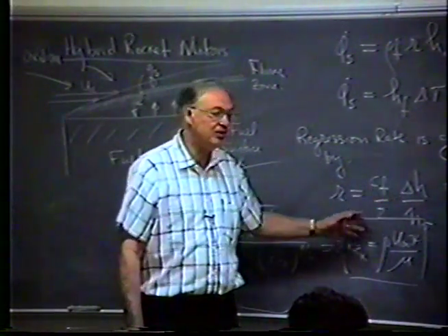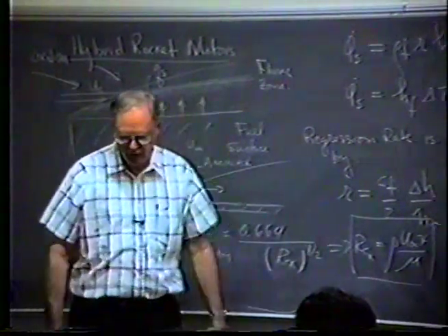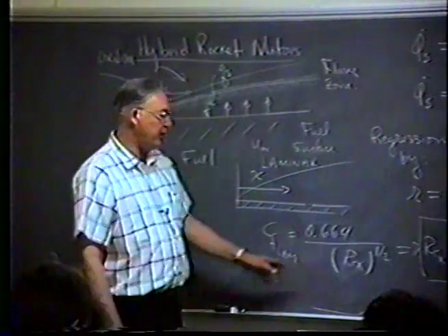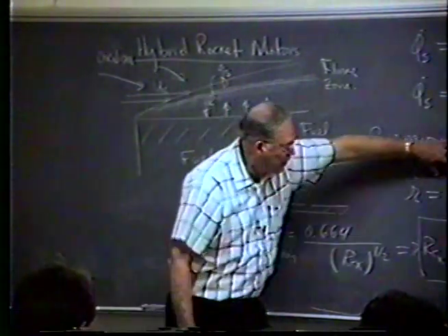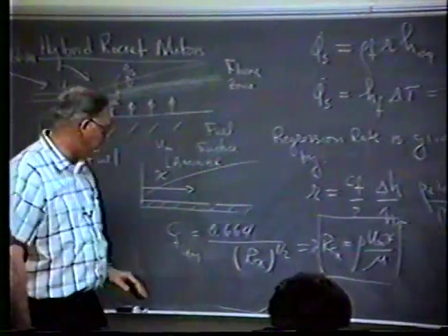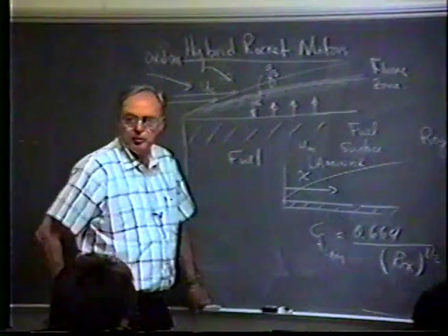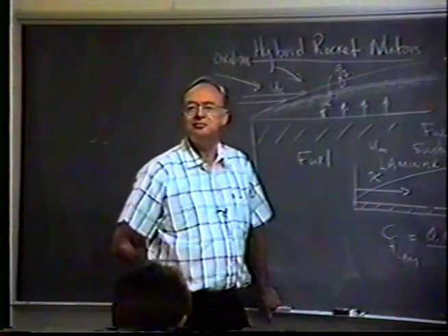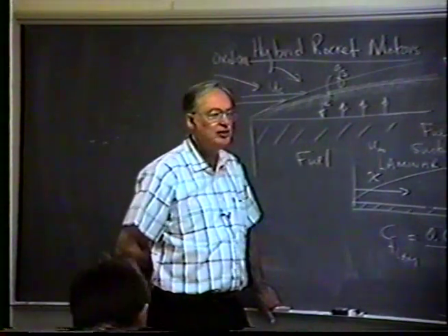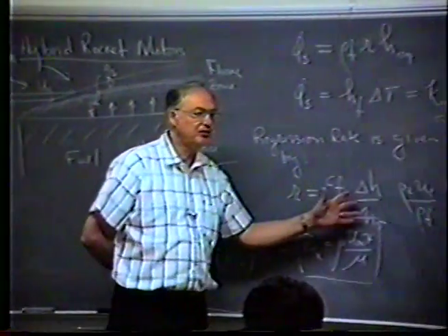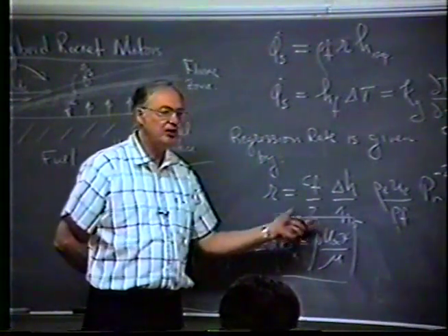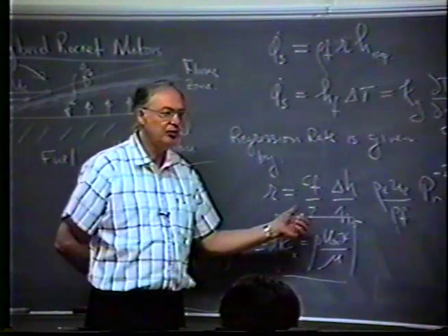So that decreases the heat transfer rate. Okay, so now, did we get this point? We're right here at C sub f over 2. What does C sub f over 2 have to do with this problem anyway? What was the term we introduced for that? Reynolds analogy. Reynolds analogy says that the heat transfer coefficient is a function of the shear stress coefficient. So this is related to the heat transfer coefficient, right? Through Reynolds analogy.